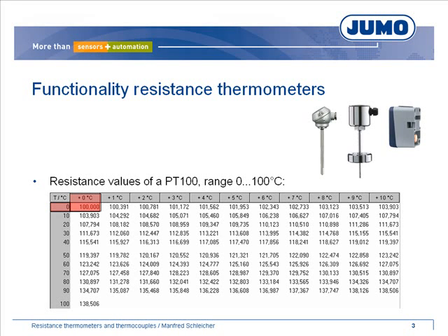At a temperature of 75 °C, 70 °C plus 5 °C, the resistance value is 128.987 ohm. Furthermore, resistance thermometers like PT1000, basic resistance 1000 ohm, PT500, basic resistance 500 ohm, and PT50, basic resistance 50 ohm are used. Generally, all kinds of basic resistances are possible.